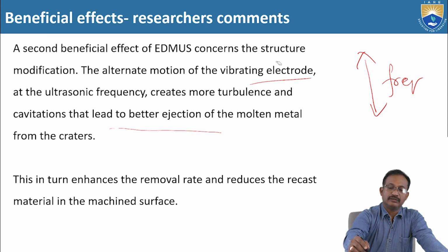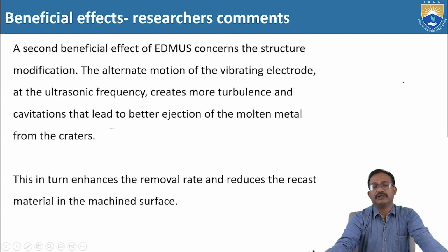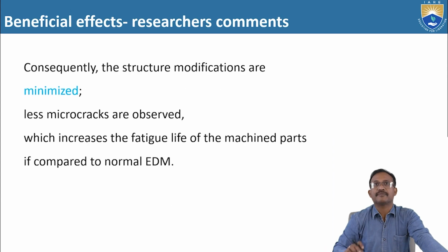However, debris impacts reduce the material removal rate, but appropriate flushing arrangements and more turbulence and vibration effect will maintain the appropriate debris in the dielectric fluid medium so that it enhances the removal rate and reduces the recast material in the machining surface.